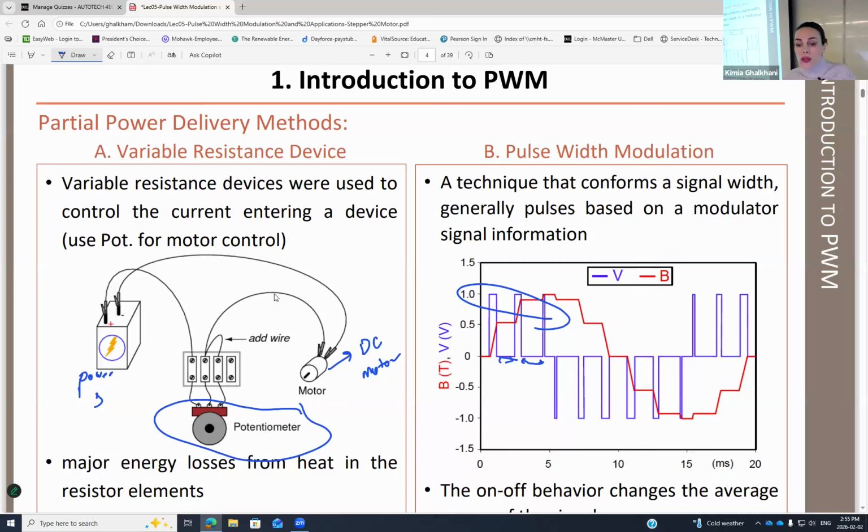It does travel through such a signal, but it is happening super fast. Suppose that you are stopped at a red light, you are not pressing the gas, and then all of a sudden you press it. Of course, even if your foot is still touching the pedal, this signal is going on and off. But it is happening super fast because pulse width modulation works based on a timer. And the way that we set the timer means we are setting for how long we want it to be on, and for how long we want it to be off.